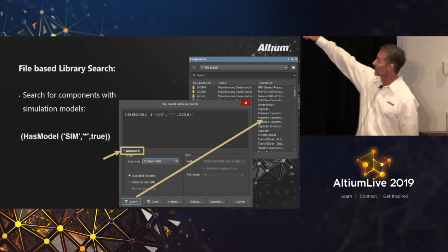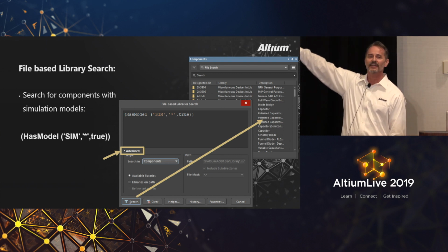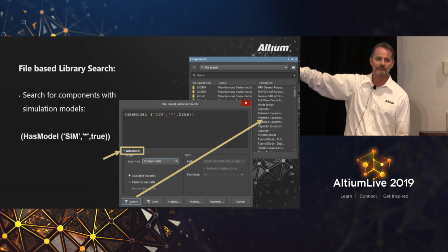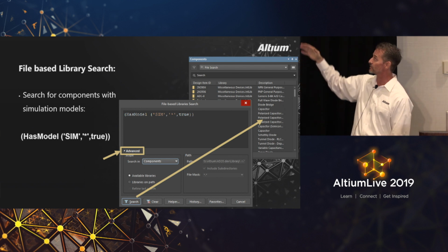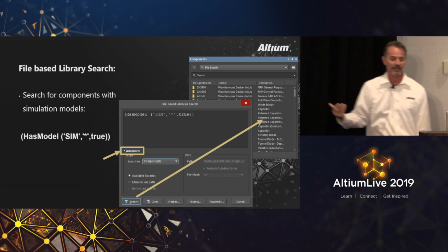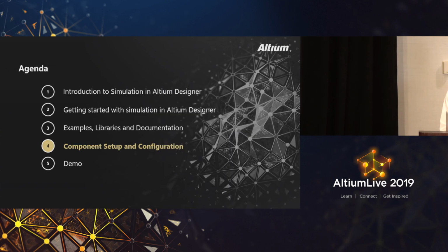What you do is you can right-click on the returned component, and it'll have an option to install that library. Just install it. Or if you try to place that component and the library is not installed to your configured libraries, it'll say, oh, your library's not configured. Do you want to add it? So you can search through your configured libraries, or even libraries you don't have configured on your hard drive.